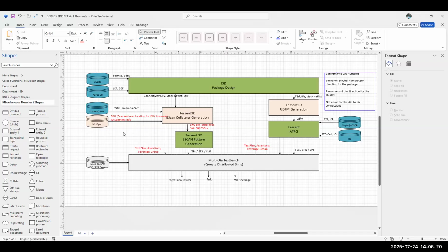And you're still going to need information, right? For some of these fuses, you have to step up the voltage, and there's a whole sequence that needs to be done to program those fuses. I don't think that goes in the format. We just need to know the pins and the mapping, and then there's a set of instructions, which I guess we could provide as an HTML document that describes how those fuses are physically programmed on the tester.